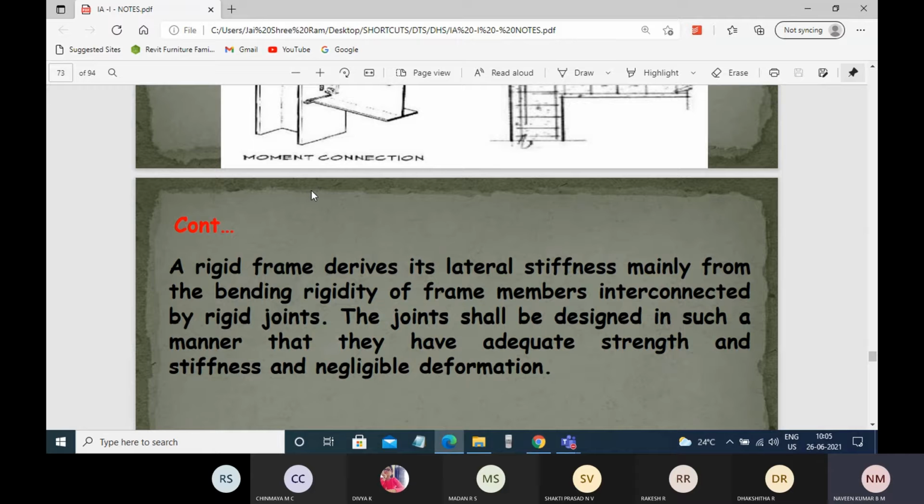you can particularly see that type of pin joint in trusses, where the trusses are designed only for forces. You will find the member forces, whether tension or compression, and what the magnitude will be, right? The moment will be zero, okay? Because a pin joint can rotate through any 360 degree angle, so the moment will be zero.